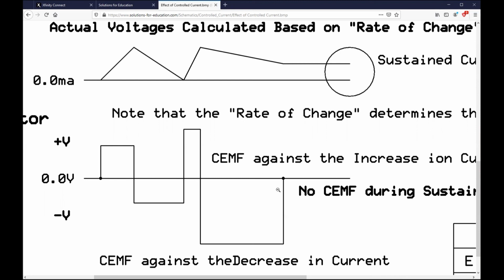How about, tell them about the bomb that can occur in inductors, particularly electric motors. Well, if an electric motor is, shall we say, stalled, all of a sudden you do not have counter EMF, and as a result, you now have full current that is not backed.